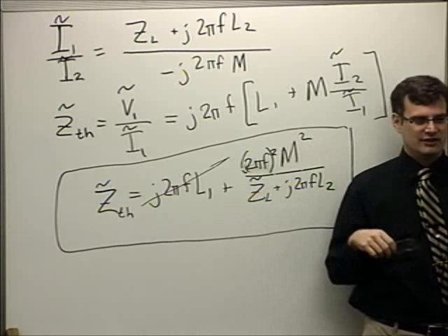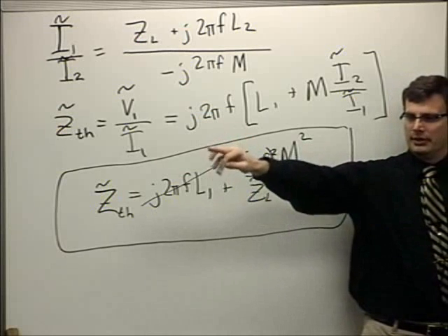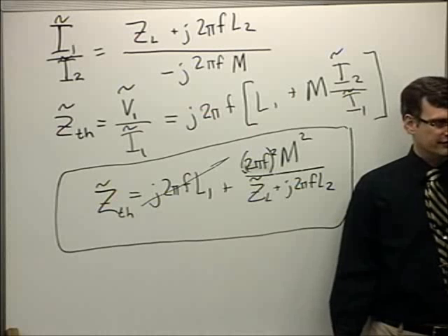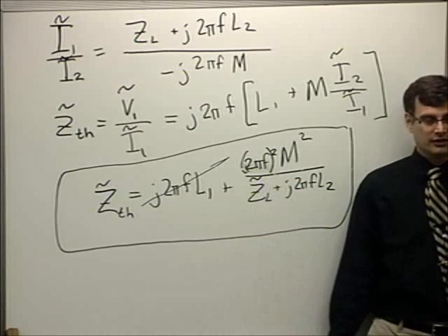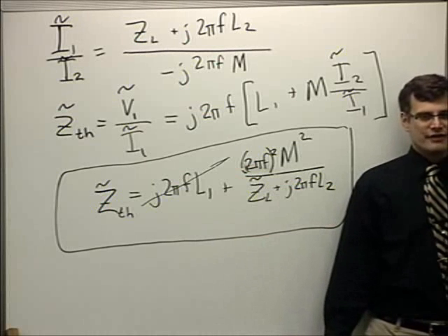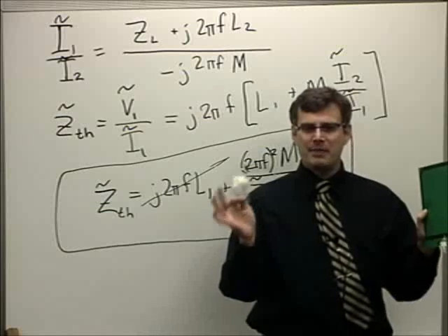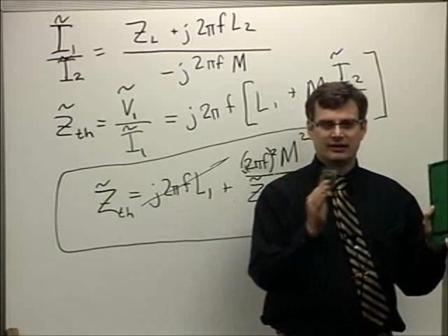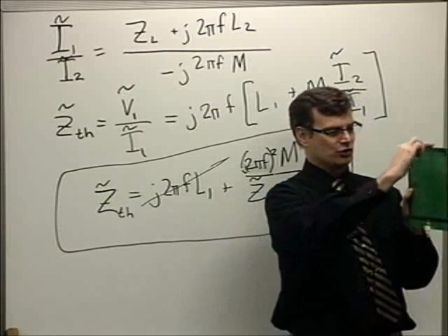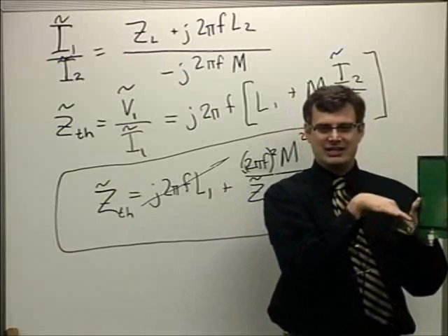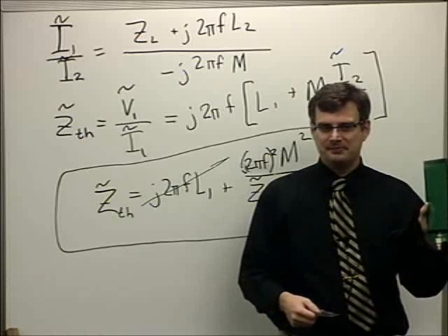I think there was a big coil, and then several meters away they were exciting a light bulb using inductive coupling. Yeah, this is very similar. You're just relying on the fact that even though they're not sharing much flux, the only way to expend power in an inductive system made out of really good conductors is through the coupling on the resonant device on the other side.